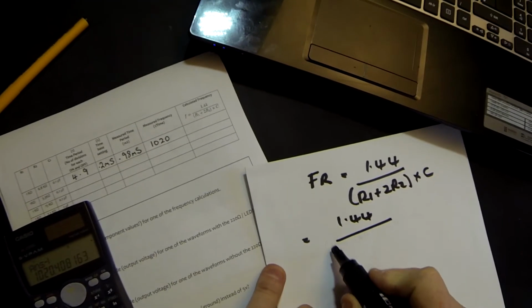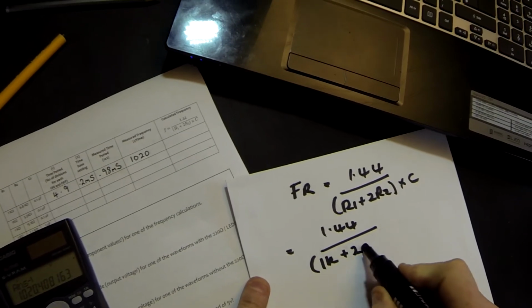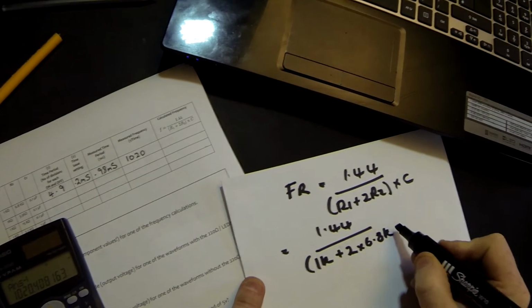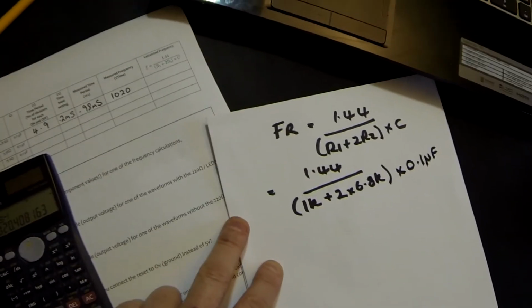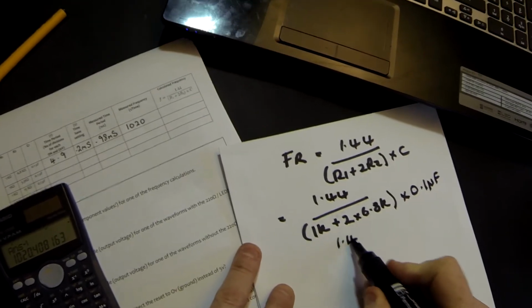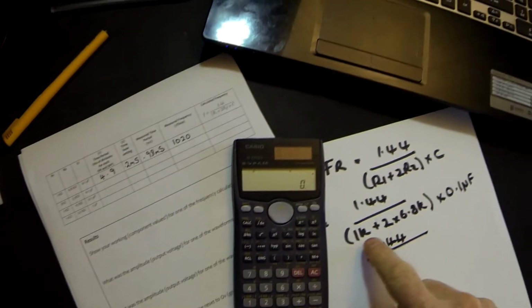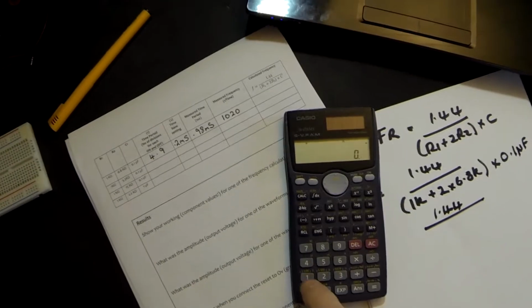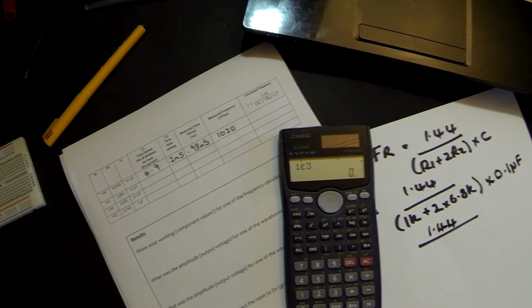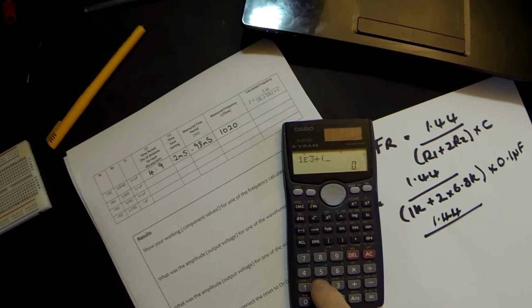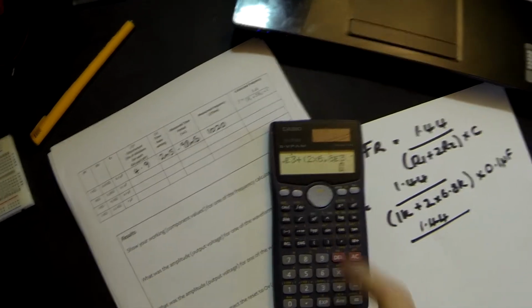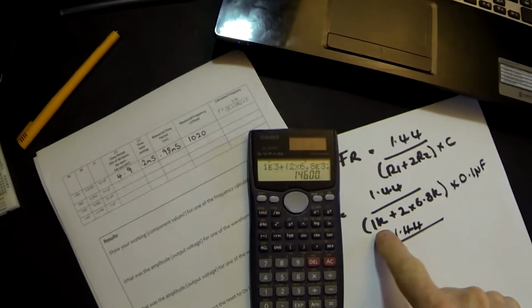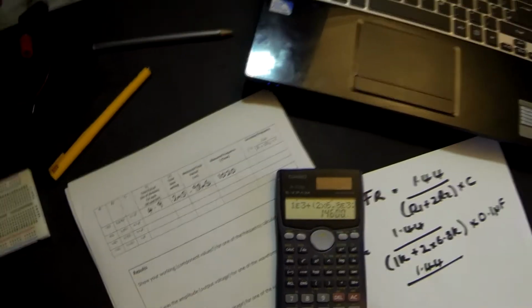1.44 divided by 1k plus 2 times 6.8k, because they were the values we used in this experiment, times 0.1 microfarads. So that's the same as 1.44 divided by, and now let's work that out. So I want to work out 1k plus 2 times 6.8k first. So 1 exponent 3 plus, open my brackets, 2 times 6.8 exponent 3, close my brackets, equals, so that's 1k plus 2 times 6.8k is equal to 14.6k,